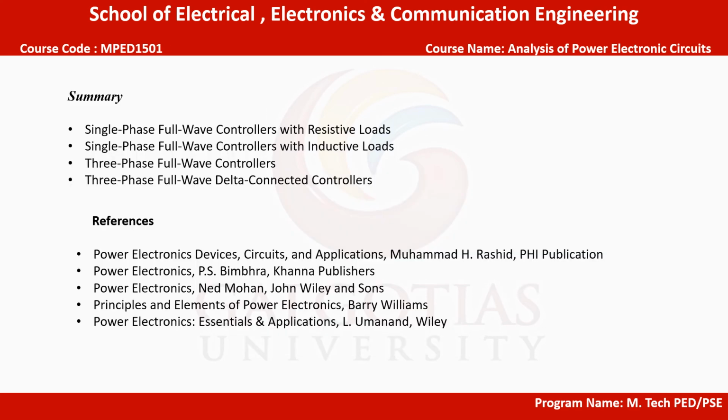So in this lecture we discussed the different types of phase control and we discussed the working principle of single phase full wave controllers with rectifier loads, single phase full wave controllers with inductive loads, three phase full wave controllers and three phase full wave delta connected controllers.